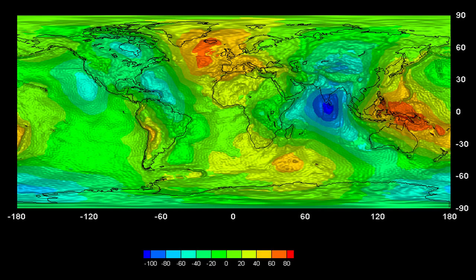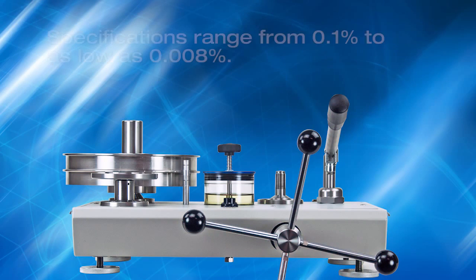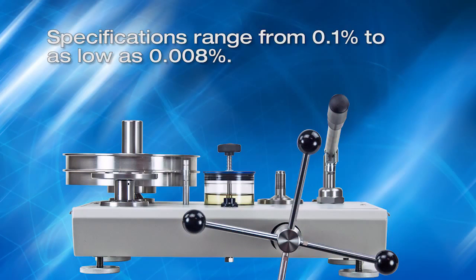For example, standard gravity is defined as 9.80665 meters per second squared. The gravity in the southern half of the United States can be as much as 0.14% different than that. If a deadweight tester is built and configured for use at standard gravity, but is then used in Houston, Texas, all pressure measurements will be off by 0.14%. In addition to gravity, other environmental conditions need to be considered, including temperature and air density. Deadweight testers available on the market today have specifications from 0.1% to as low as 0.008%.